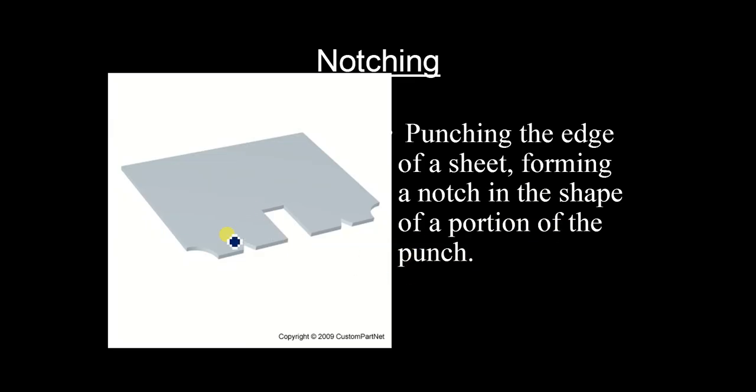Clear? So obviously, if we want to remove certain material in different forms, we require a punch, and the punch should have the particular form which we require. In this particular case, the punch had an arc over here. That is the reason that when the punch was applied over here, the scrap was removed. This kind of scrap was removed, and the leftover is a notch.